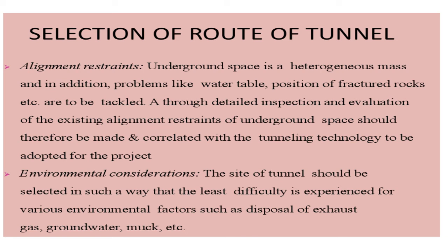Coming to the environmental consideration, the site of the tunnel should be selected in such a way that the least difficulty is experienced for various environmental factors like disposal of exhaust gas, groundwater, muck, etc. So when you are going for environmental considerations, it means that sometimes you may be required to cut through the ground. While cutting, you will have a lot of soil or rock. So cutting and filling has to be done. So you have to consider the geological formation.